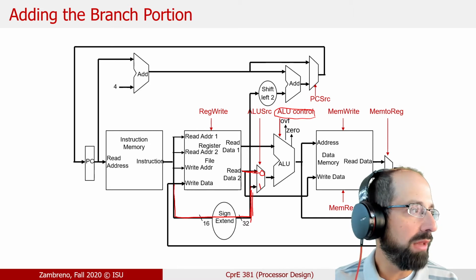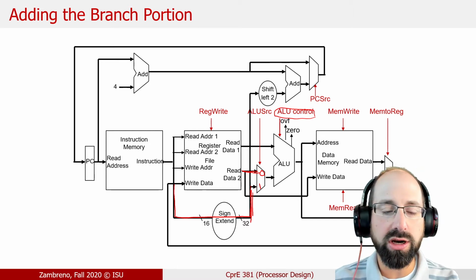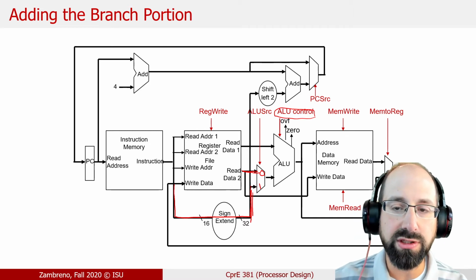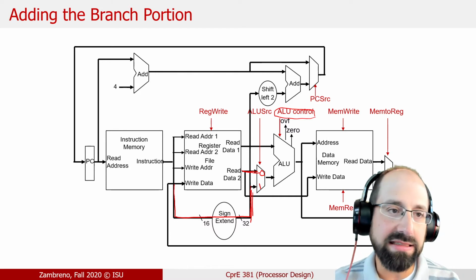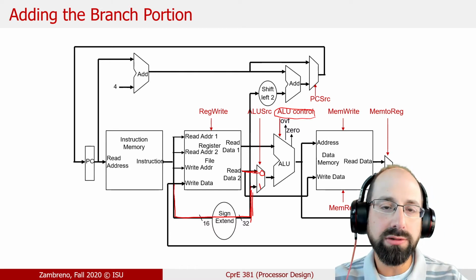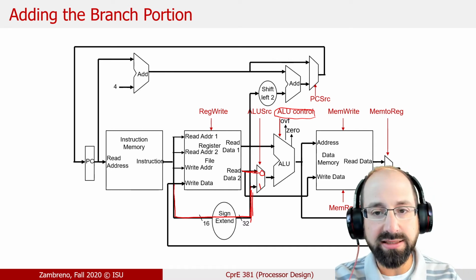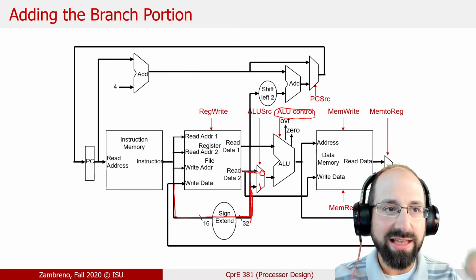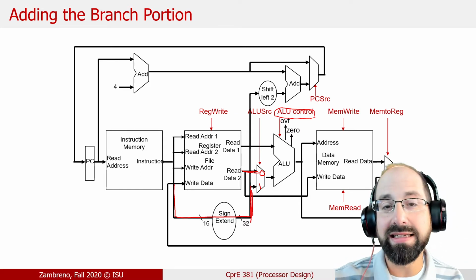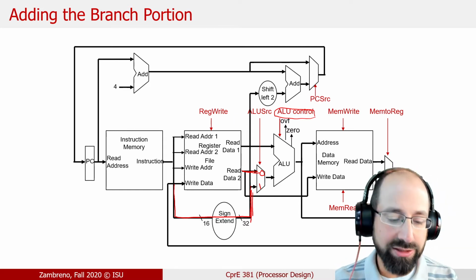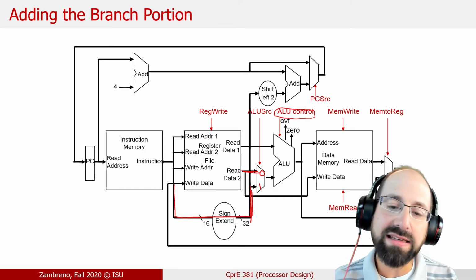My only suggestion may be to be very conscious regarding the names you choose for those control signals. They should have something that is human readable and meaningful to you and your team when you're able to look at that signal both in a spreadsheet as well as in a waveform as well as on a diagram. All of those three things you're going to have to be consistently connecting to each other, right?